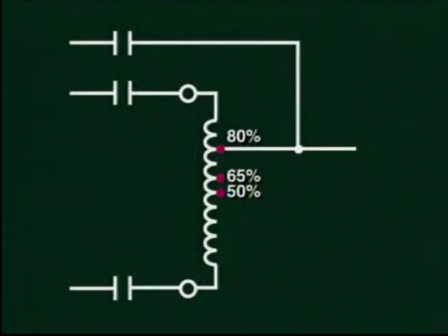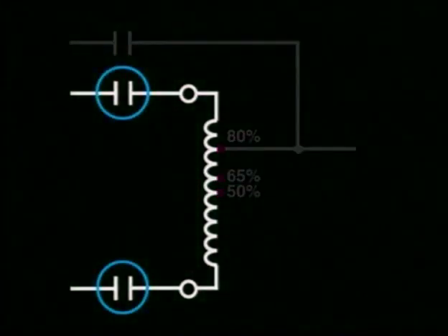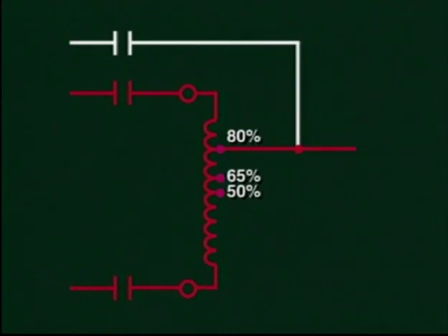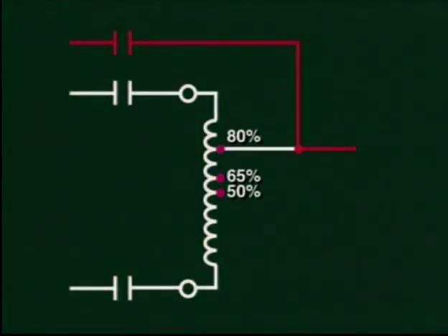The starter circuit for the autotransformer includes 2 contacts which are used to bring the autotransformer online to provide the voltage to the motor. When the motor has had a partial start, the starter's full voltage contacts close to bypass the autotransformer and provide full voltage to the motor.